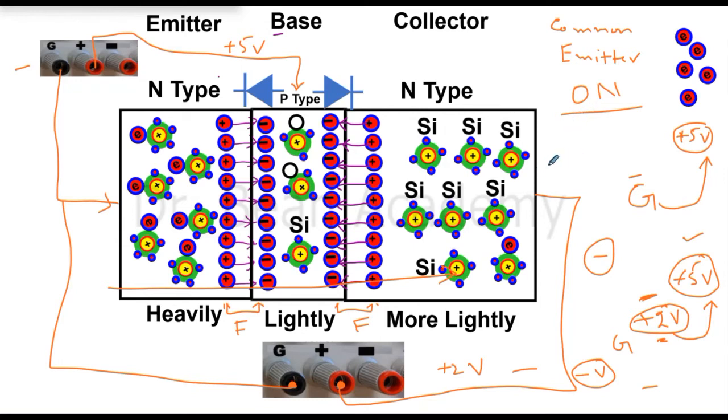This is not very desirable, but in this case it will work as on. Like now the transistor is totally on. The first case, in which both junctions were in reverse bias, it was off. Now this is in saturation mode. The current will flow throughout this device, and there is nothing special in this mode of operation, right?